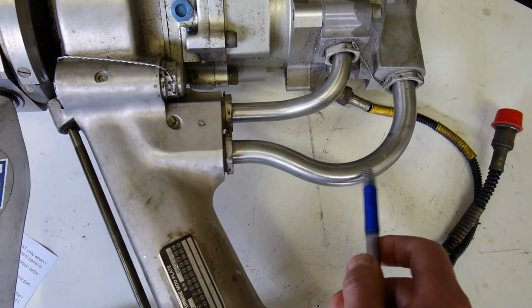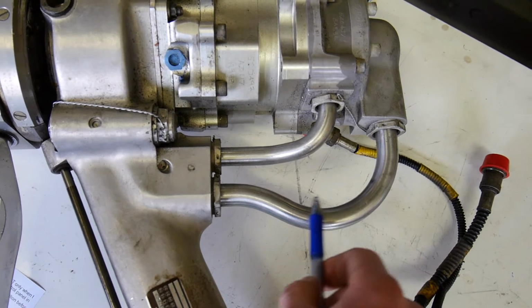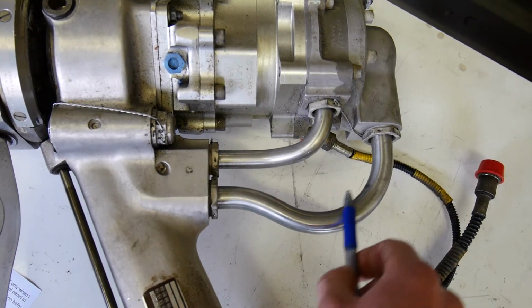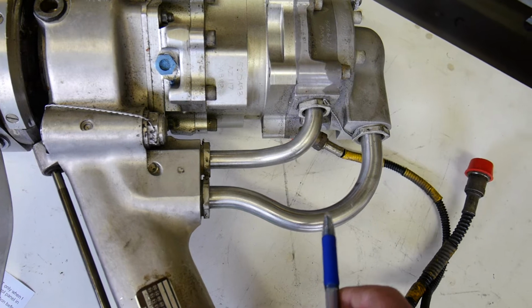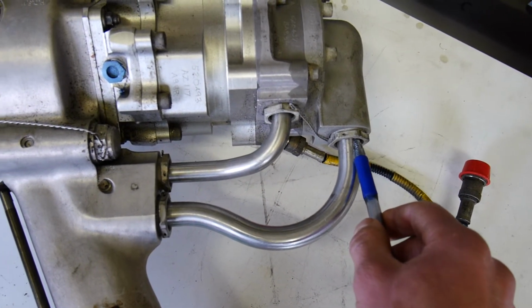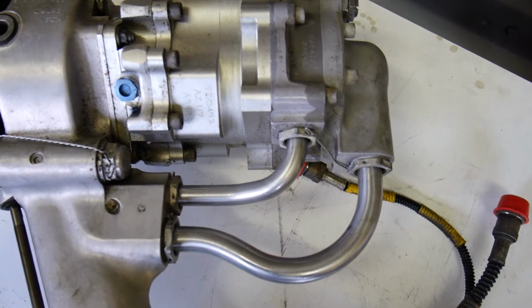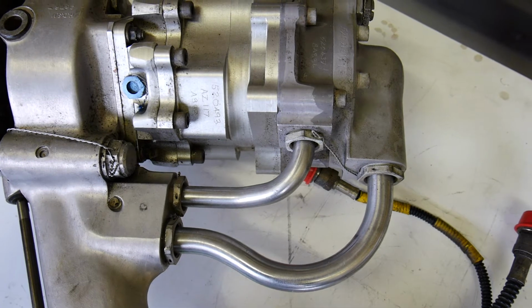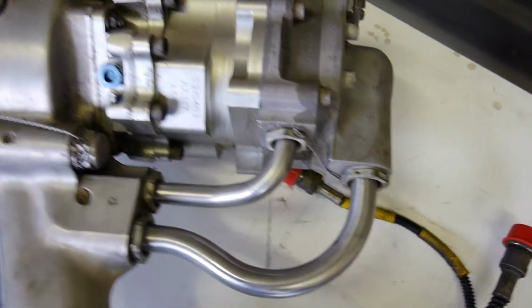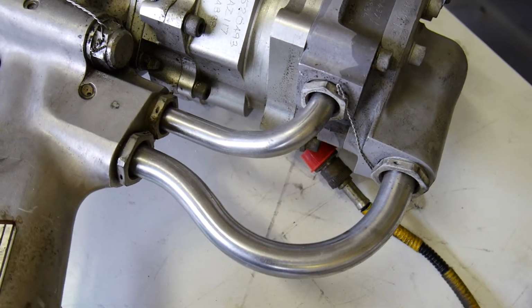The bigger diameter is required in order to reduce friction in the flow, and therefore we get slightly higher pressure at the intake, and therefore there is less probability of cavitation of the hydraulic pump. So that's how you trade off between the two diameters.